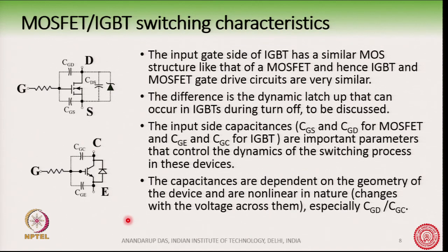So, here you can see that there are capacitances CGD, CGS, CGC, CGE. They originate from the structure, the geometry of the device. And the basic idea of this switching characteristic is that we have to charge or discharge these capacitors.